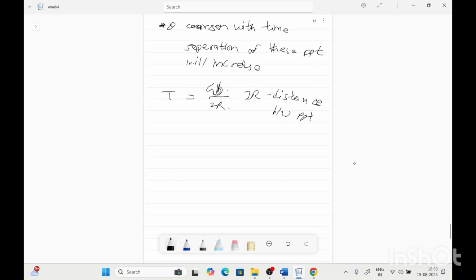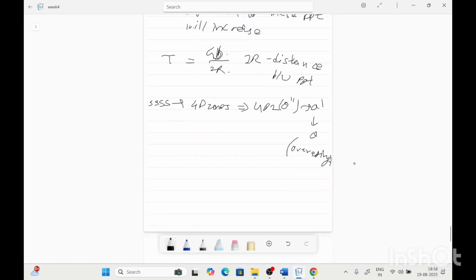So up to this point we discussed that the supersaturated solid solution first forms the GP1 zones and then GP2 zones, which is known as the theta double prime. Then it will change to theta prime and it will change to theta with overaging. According to the different heat treatable aluminum alloys, these steps will also differ.